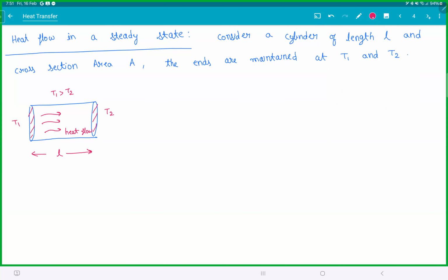Okay. So this, again completely experimental, dQ/dt, that's your heat flow, is given by minus KA by L times (T2 minus T1). Here, dQ/dt is your heat flow per second.